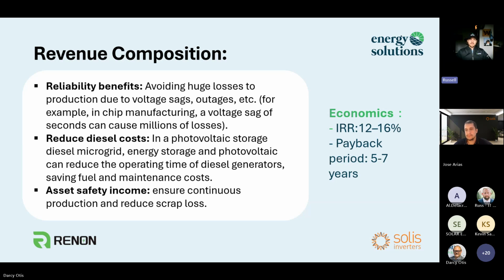A lot of the time when you're looking at solar returns, you're looking at roughly a 10-year threshold just by having the solar producing energy during the day to offset some of your energy costs during the day. And this works well for some manufacturing facilities where they do have their highest peak consumption during the day. But a lot of the time places are running 3 shifts. So you'll see, and granted it's cheaper energy overnight, but the peak demands will still show up even if it's an off hours time.